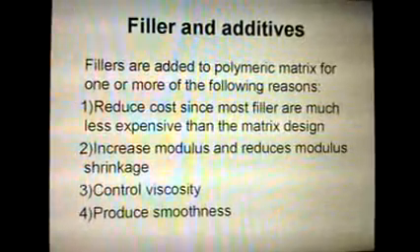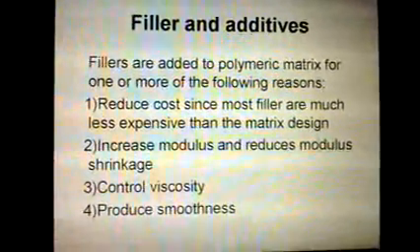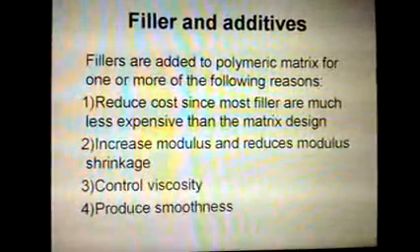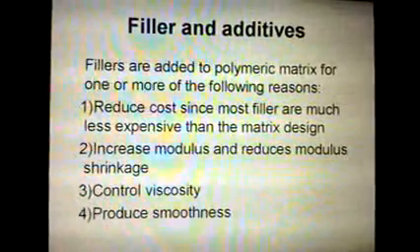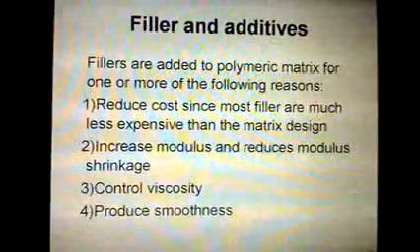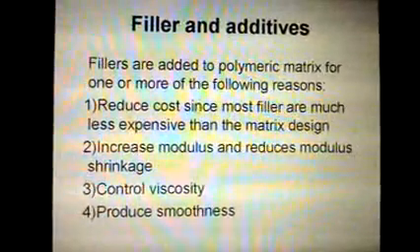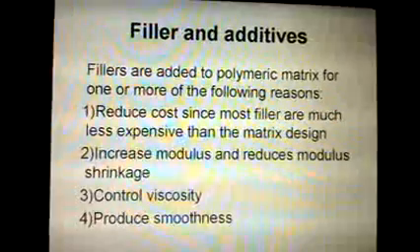And we will see now filler and additives. Fillers are added to polymer matrix for one or more of the following reasons: reduce cost, since most fillers are much less expensive than matrix design; increase modulus and reduce shrinkage; control viscosity and produce smoothness.